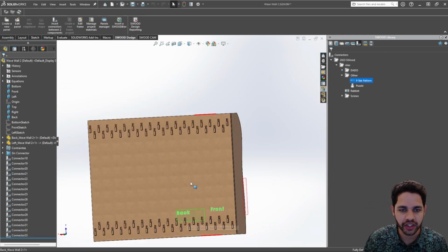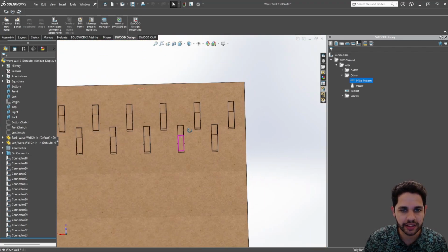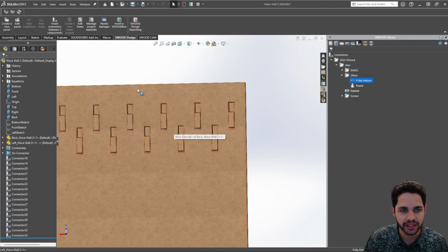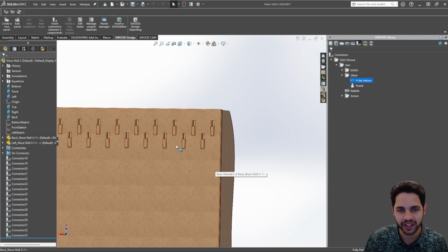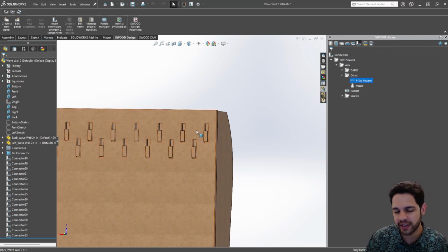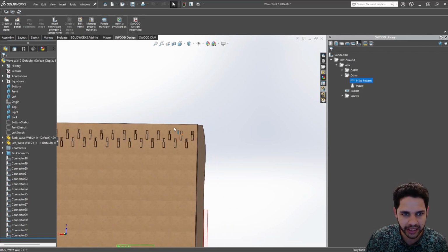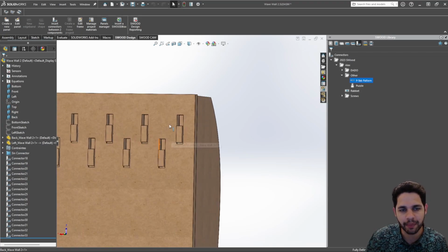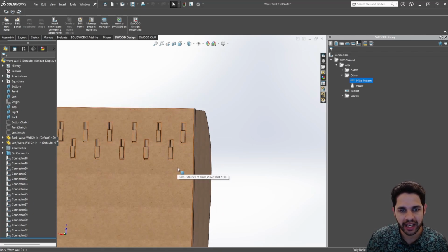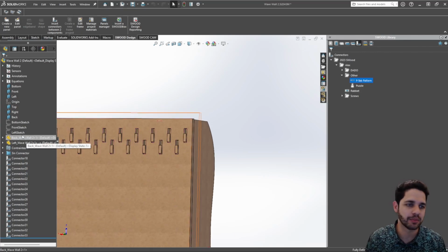As you can see, that's offset there. So when you go to machine this in place, it's not as cluttered and you have more structural strength. If these were all right next to each other, I feel like the structural integrity of this backboard would be more likely to split down the middle here. Whereas when it's offset, and probably having an offset of even more, like maybe instead of 3 and 5, I'd want that at 3 and 8 or something, further down here, just to add some strength to it.